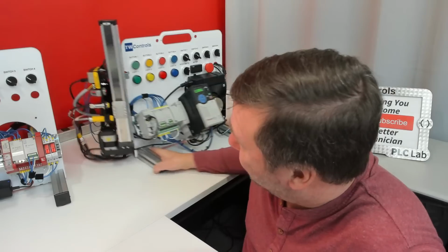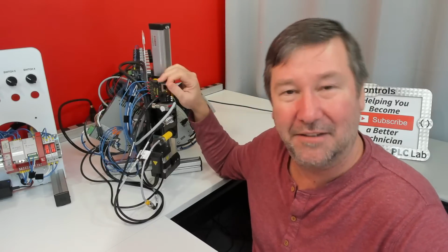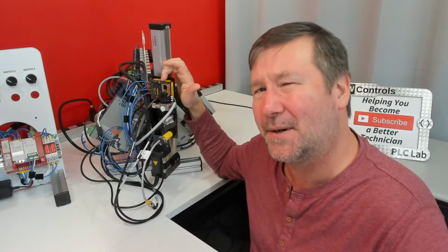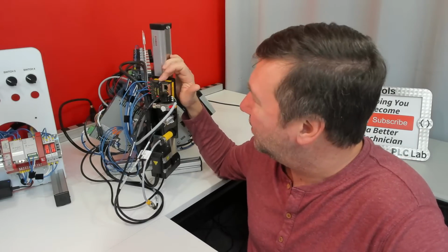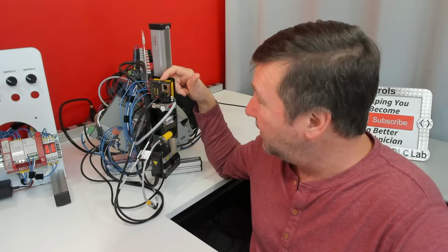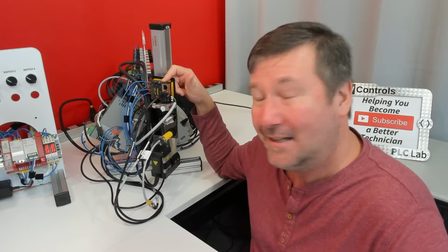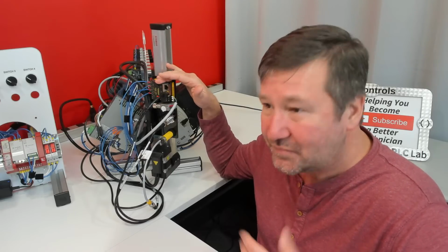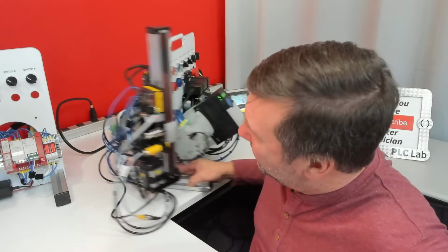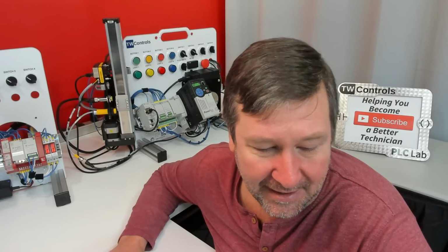Since we're talking about that, that's one thing I love about the Turck module and many others, but this one right here especially. Arguably, this is probably the best IO-Link module on the market to get something operating as fast as possible. This does EtherNet/IP, Profinet, and Modbus TCP with zero configuration. It can actually serve up all three at the same time. And yes, you can't go in there and disable the different ones, but that's what I like about it: you can grab it and go pretty fast. Now, I didn't say it was 100% the best in the end.